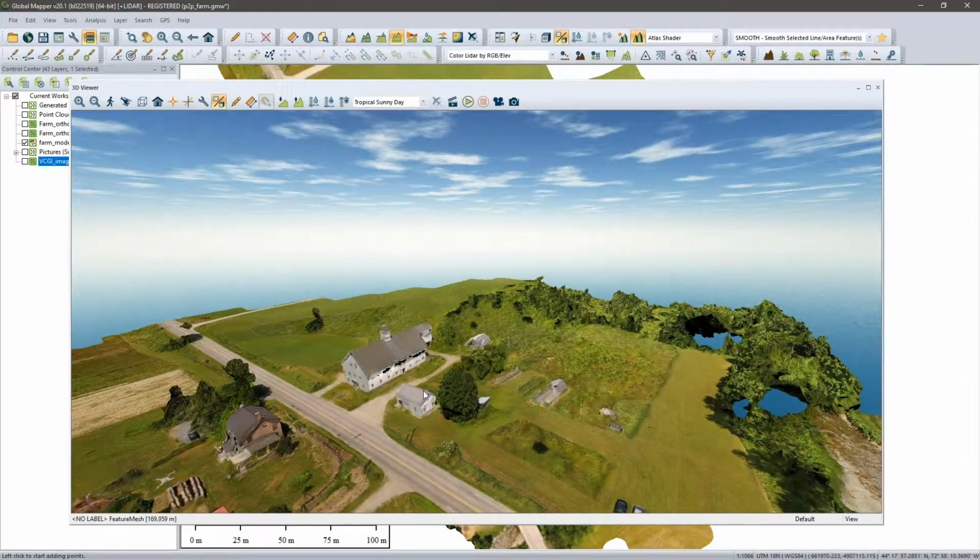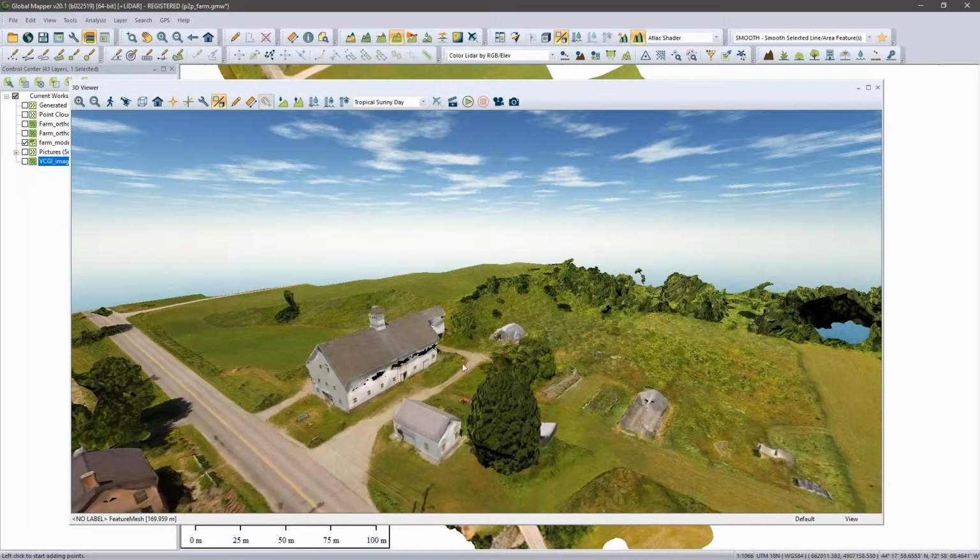It was nice to hear from Anthony what height he flies his drone at. Certainly it depends on what kind of data you are collecting. In this case, this was flown fairly high, probably a similar height to what Anthony was talking about. Mostly focused on the terrain information. So you don't get quite as good detail where some of the buildings are. You do want to get some nice low photos if you're trying to do good 3D building reconstruction. Make sure you get a photo up underneath the eaves as well.